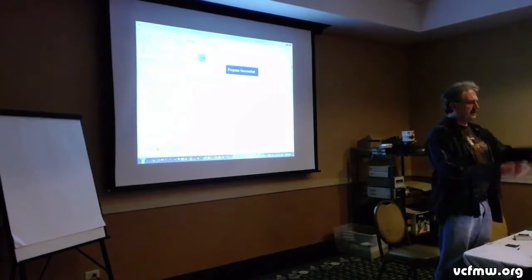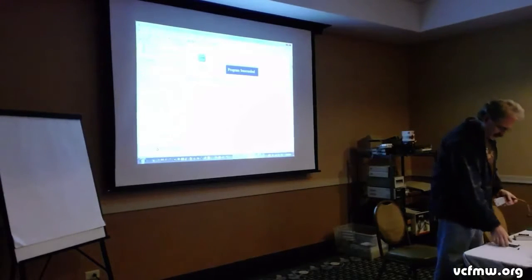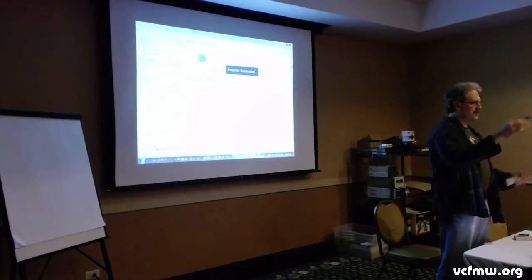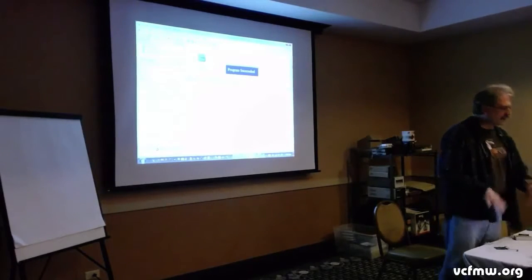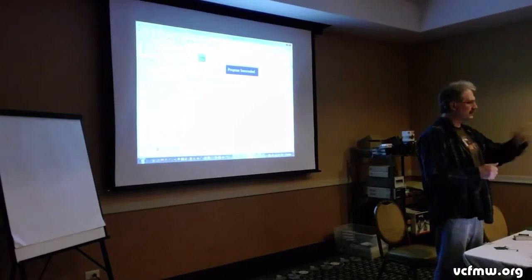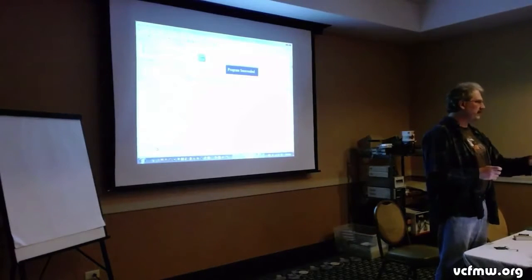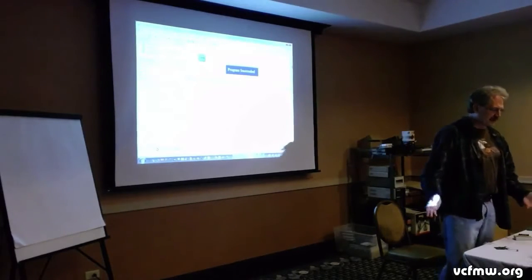And on the end of it, it's a 2x5 connector right there. And so magically that 2x5 connector goes right onto the end of this connector right here, which has 4 I/O signals that are always on the CPLD port. You just run the wires out. And then there's 3.3 volts or VREF and ground. So that's your 6 signals, right? So once that was done,